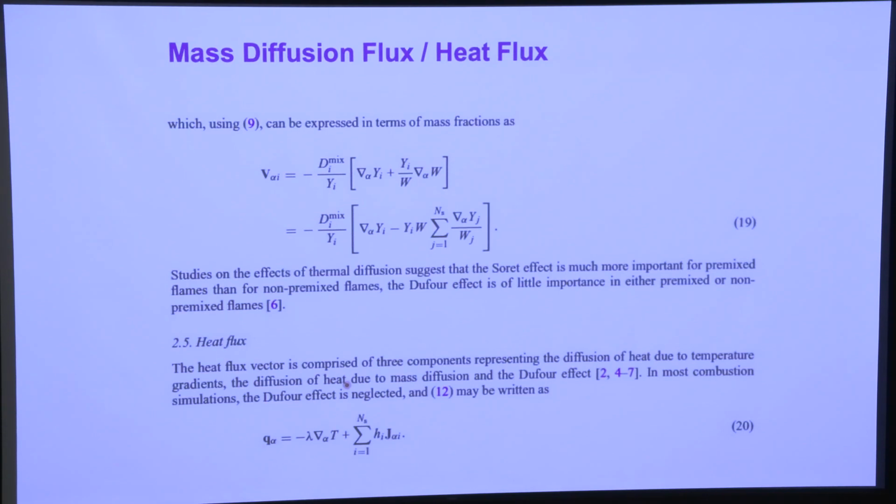The heat flux vector is comprised of three components representing diffusion of heat due to temperature gradients, and the diffusion of heat due to mass diffusion and Dufour effect. Again, here, in most combustion, the heat flux vector retains only the heat conduction term plus the flux that's transported by the species diffusion. We usually neglect the Dufour effect.